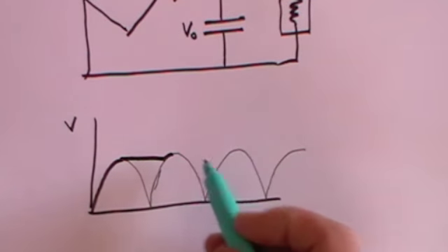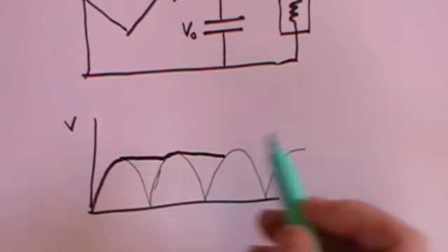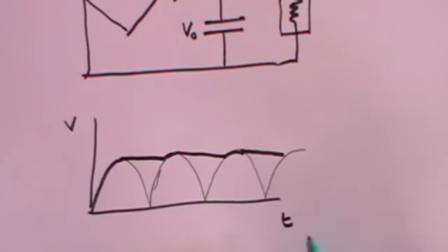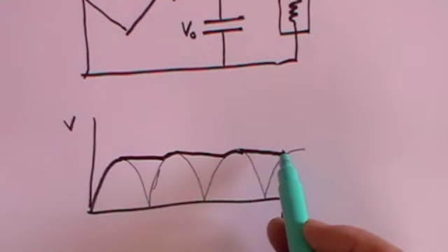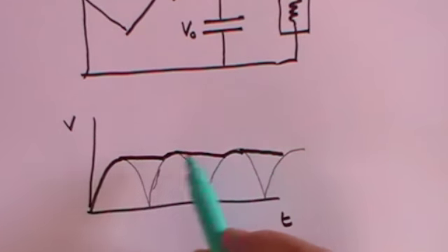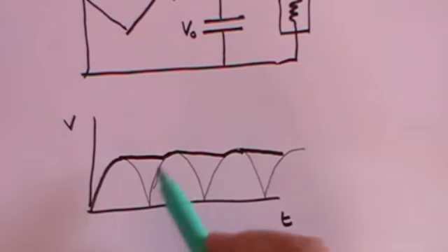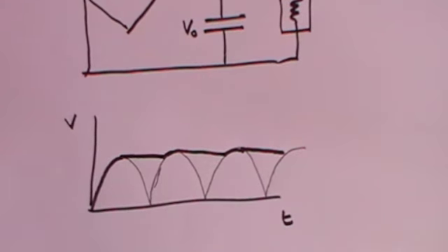Then the current falls down, but the capacitor holds its voltage. And then the same thing applies again. So what you've got now is not a perfect direct voltage or direct current, but almost. There's a slight wobble in the voltage, but nowhere near as much as there would be if you just had it like this. And that will enable the computers to work much more satisfactorily.